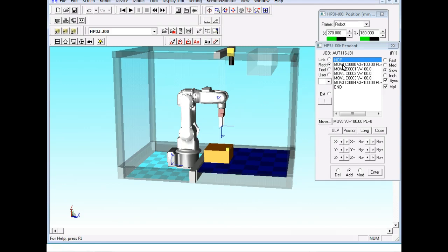All you got to do is learn what a linear move is, what a joint move is, what a circular move is, what a spline move is, and how do you round off, how do you make it cut the corners and that kind of stuff. And you can literally make a point-to-point robot follow any path you need to follow.